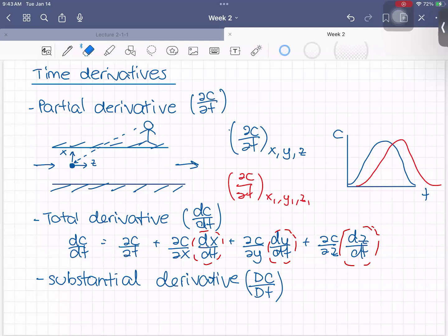The observer is no longer on the motorboat, but right now he's on a raft. Let's say this is a raft, meaning that he's moving with the same speed as the flow of fluid. So this is the flow of fluid, and he's moving along at the same speed too. So the concentration change with time that he can see is going to be in terms of the substantial derivative now, Dc by Dt equal to, let me write it first and I'll explain later.